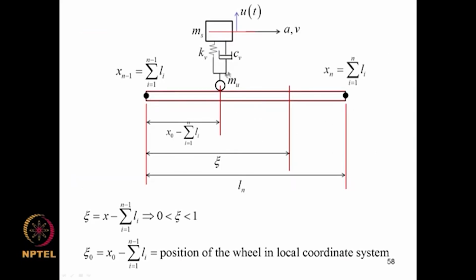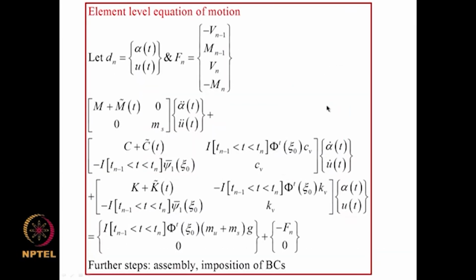To deal with the second type of problems, we considered a beam carrying a moving single degree of freedom system, and we formulated the governing equation and developed a finite element model based on weak formulation, and showed that the element mass matrix, damping matrix and stiffness matrices are unsymmetric and time dependent for this class of problems. The interaction between the vehicle and the structure induces these unusual features. So these types of problems need to be handled only in time. They do not have natural coordinates; the concept of natural frequencies and mode shapes is no longer valid.